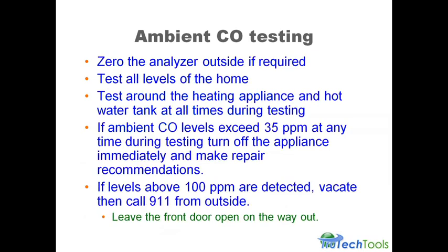Zero the analyzer outside if required. Almost all of them do. Now, the personal alarms like the Sensit P100 and the Testo 317-3, those are absolute sensors, so they do not require zeroing in fresh air. They're always on. They're making an absolute reading. They're not a relative sensor like a combustion analyzer.